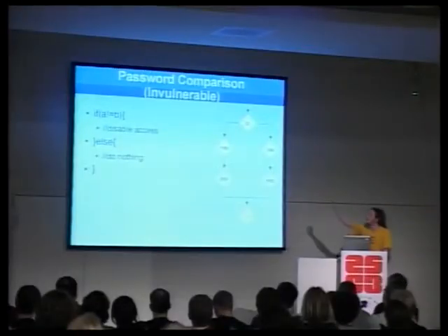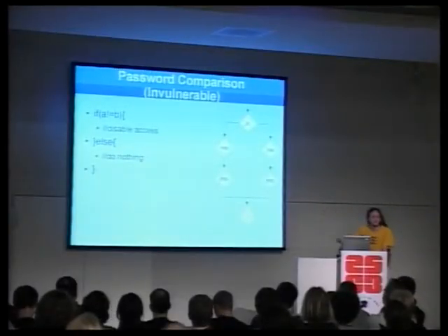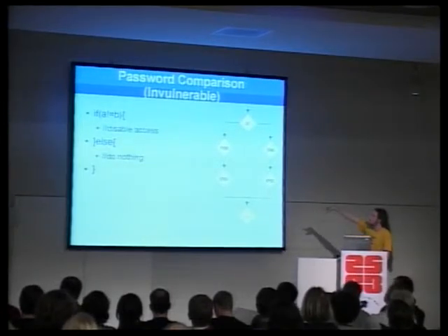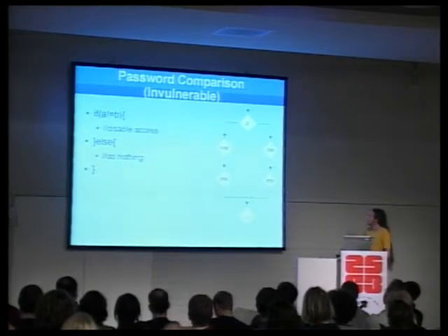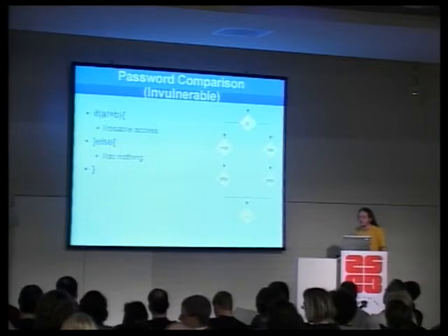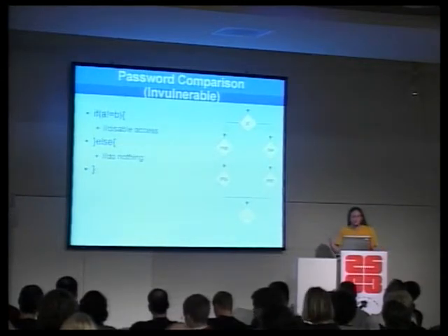Neither of these does anything except make sure that it gets to the end and that it does it at the same time as it would take if it went the right route. On the right route, it runs a bit immediate set, which disables access to the password-protected regions. Following this, there's a jump, again, keeping the timing balanced. So then at the end, 6 clock cycles have passed, whichever direction you went.